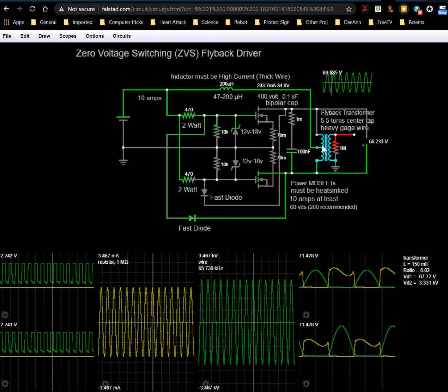But at any rate, since the inductance will change, same thing in a flyback transformer, because depending on whether you have the load or not, that will be reflected into the actual inductance of your coil. So it'll change the frequency, because it changes the L term in the 1 over 2 pi radical LC thing.